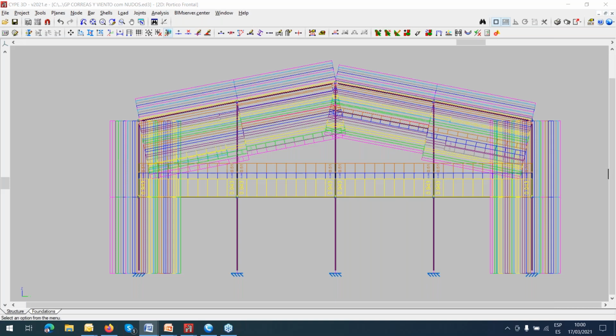But at the same time, what you get by default is all these live loads, dead loads, wind loads automatically. It's really important. Another use of the particle frame generator is that if you have a marquee, for example, a parking lot where you want to protect the cars, and you have only one section, suppose this is the right section you have here, just this part, in that case you can also use the particle frame generator and introduce the same geometry, the same size, on both sides.